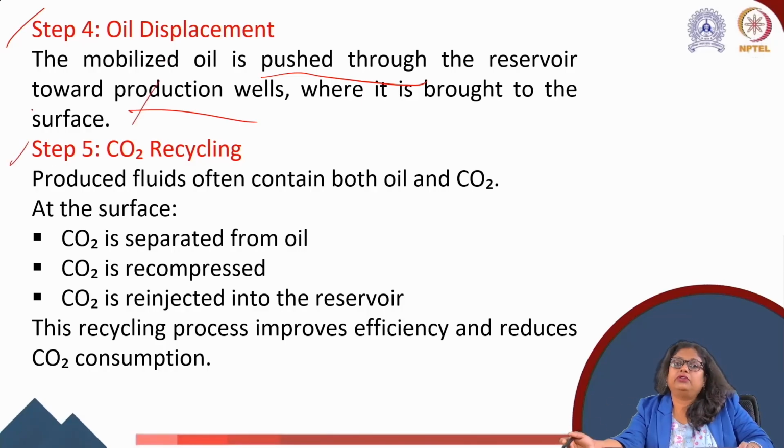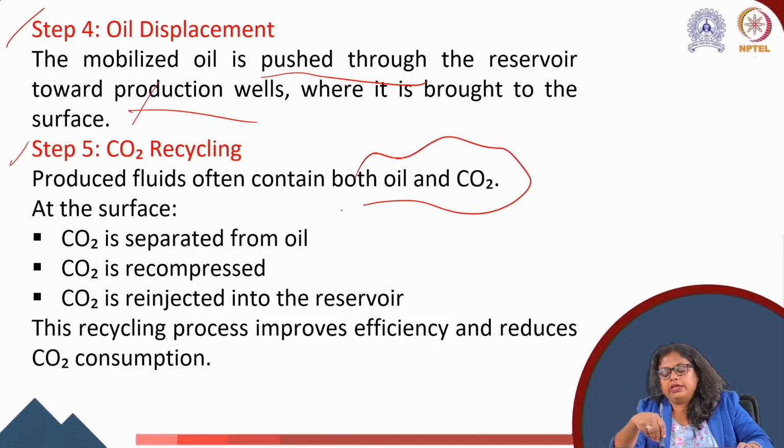And then the fifth step is CO2 recycling. The produced fluid often contains both oil and CO2, and we want to recycle this CO2. At the surface, CO2 is separated from the oil. Then CO2 is recompressed, because the pressure has been reduced and we need to re-inject it.